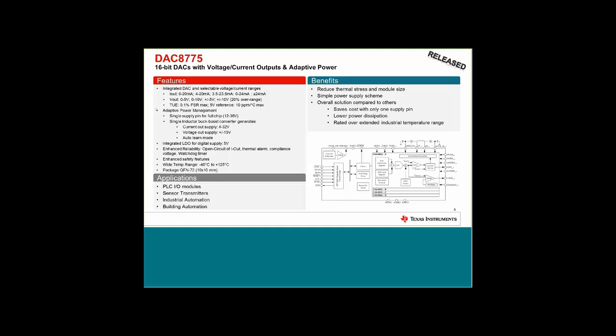Again, really the principal purpose is to drive current or voltage into a load. I guess you could maybe try to use clamp mode and the current output readback to detect what kind of load you're driving along with the compliance voltage alarm, but it would definitely not be 16 bits of resolution to detect load impedance.